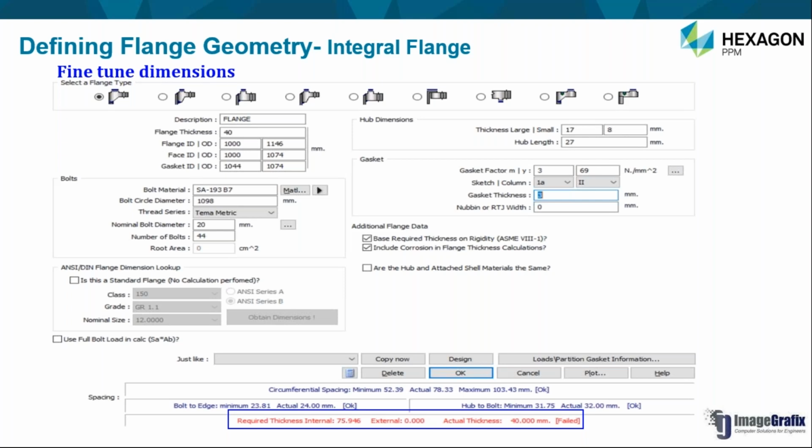Okay. So at low pressure, where your gasket parameters or the gasket seating stresses have higher values and the bolt load for the seating of the gaskets is more, there we should design the flange in such a way that your gasket is placed as near to the PCD as it can be. Okay, but for higher pressure, your gasket factors or your gasket is not controlling the design. So there you can have the gasket placed anywhere. So it doesn't make much of a difference.